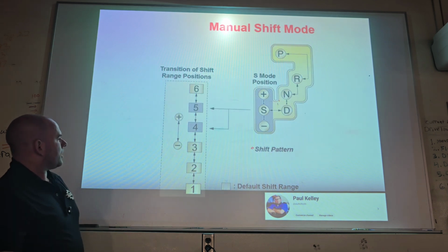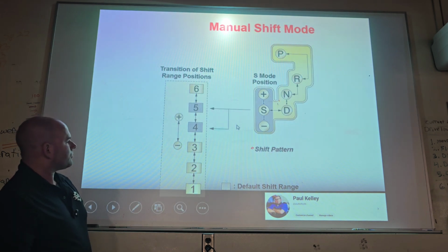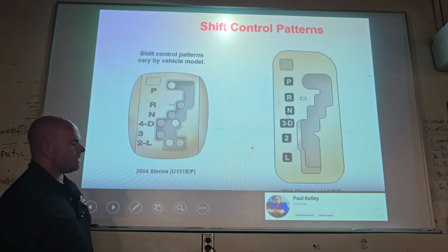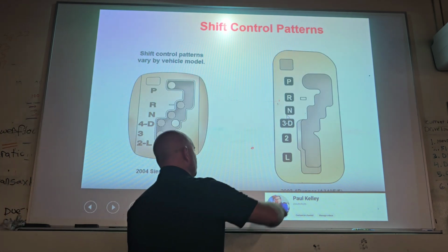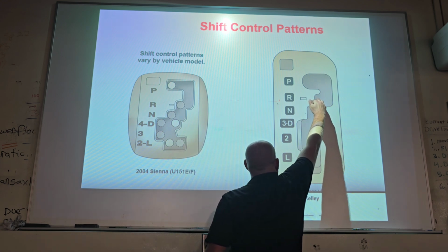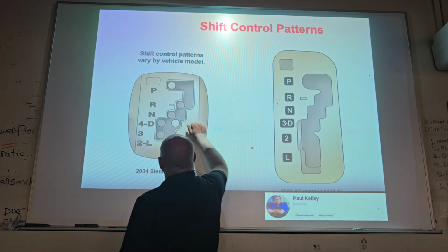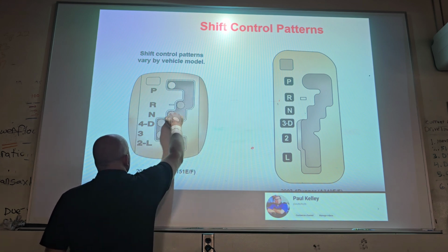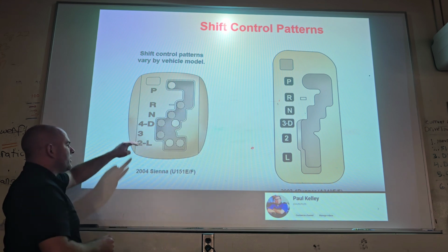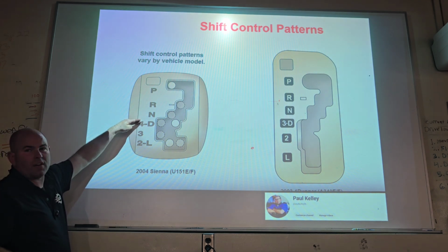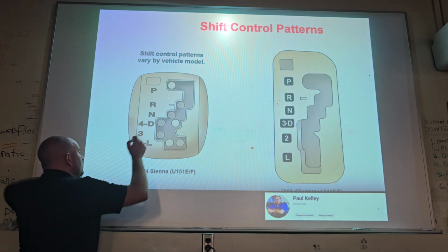And then this also talked about the manual shift mode. Okay? And then you have some like this. When we're talking about moving it into low, that's when you're like, here you go, drive, or then 2, and then low down here. This one: reverse, neutral, drive. 3rd is basically like turning overdrive off. 4th in this case is overdrive. On a Honda, they'll actually do this.